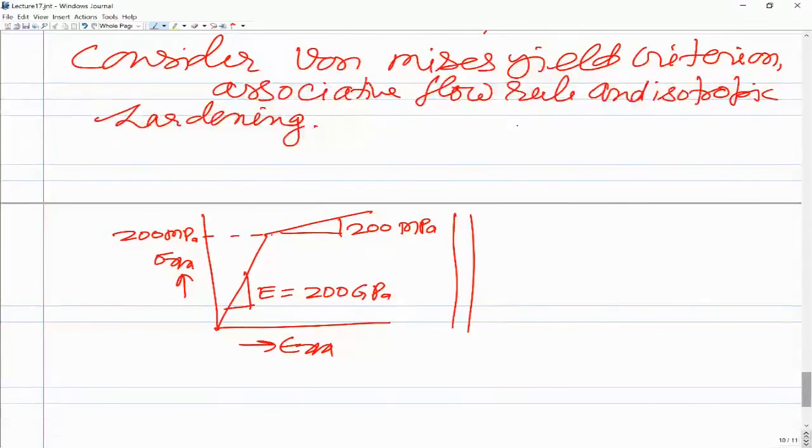plasticity, I am giving you single element idealization. Although it will not give you accurate results, that is for sure. But we are just getting to how to do the elastoplastic analysis for a simple problem. That is why I am giving this. Yes, you need more elements for an accurate solution, that is right. But to avoid the complexities associated with that, I am making it a single element. So you will use 2 by 2 Gauss quadrature, so 4 Gauss points will be there. All the calculations you have to do at all those 4 Gauss points.